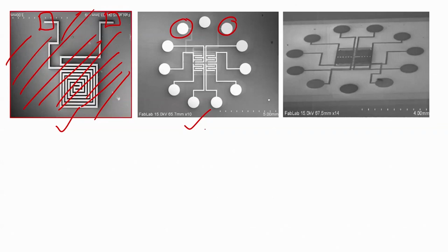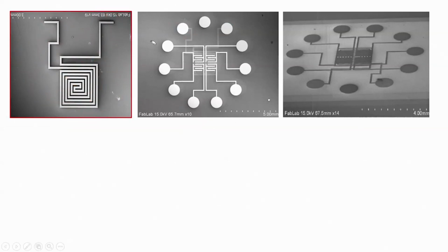On this chip, the next step is to have a piezoresistive material. How do we first deposit and then pattern this piezoresistive material? We can use several piezoresistive materials, including silicon: we can make a piezoresistor with polysilicon, or we can use a conducting polymer called PEDOT:PSS.